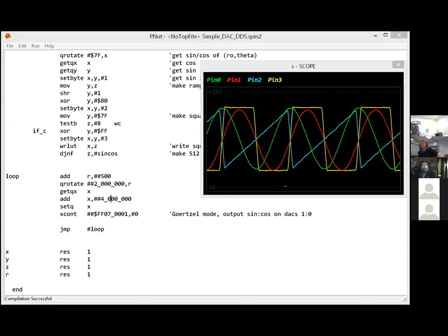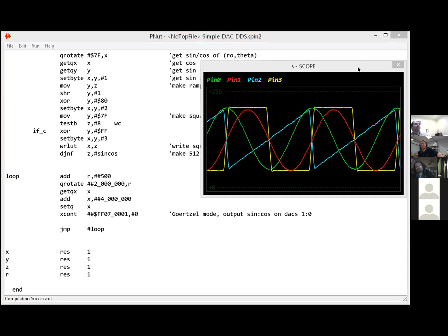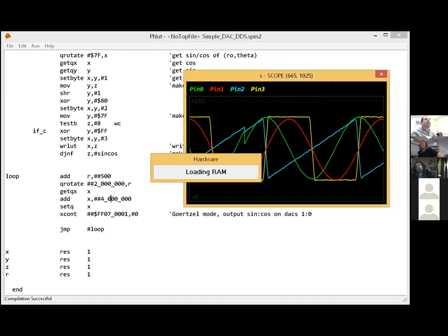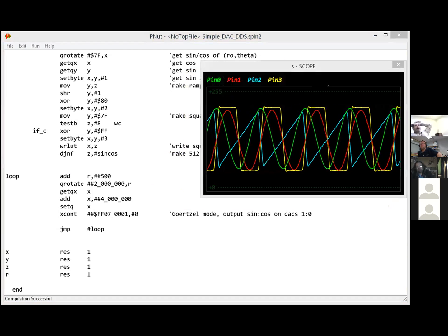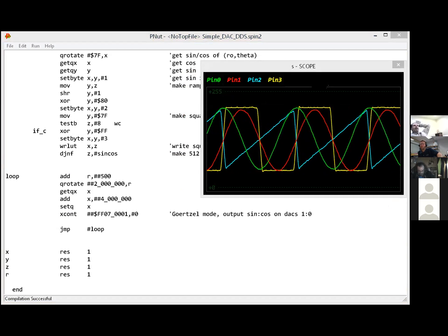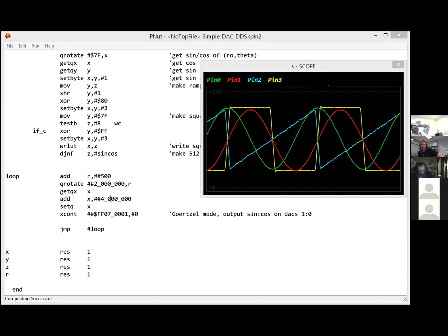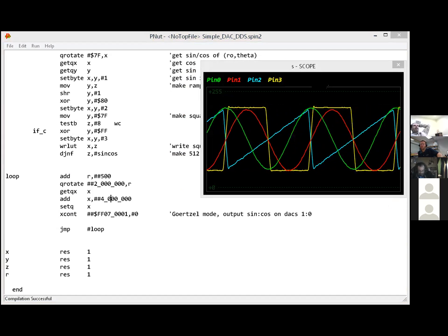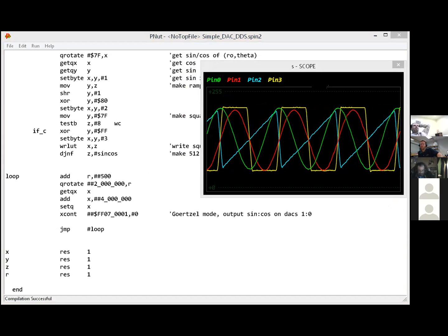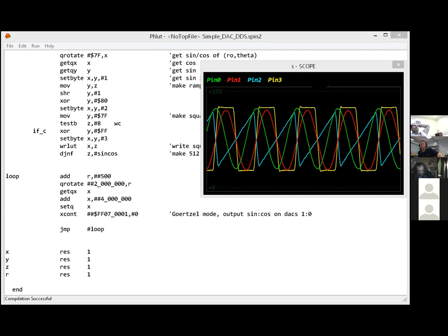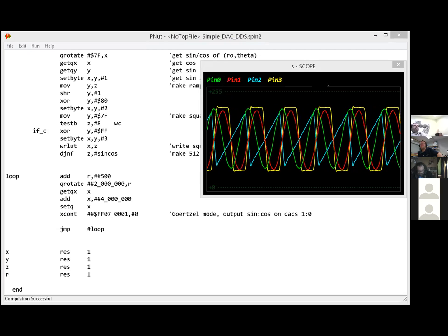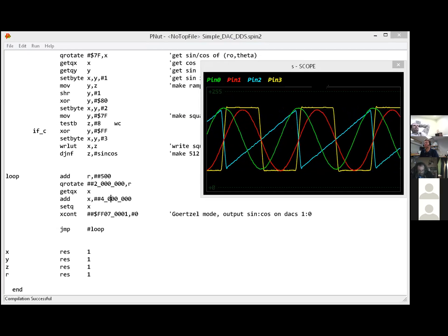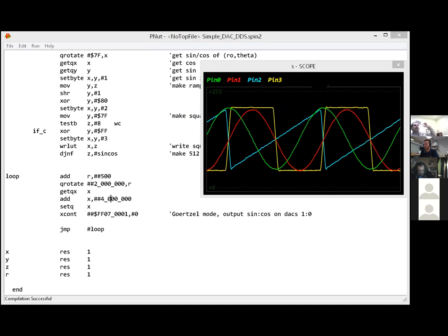Okay, so someone was asking last week, can you do a function generator? Well, here's one. Because I moved the LUT, I messed up the timing. Because the LUT has 4 bytes and each DAC channel is 8 bits, it can output 4 concurrent 8-bit channels live. And the period on this is not super high, but it could be very high. But I slowed it down so that we get nice crisp edges on the square wave.